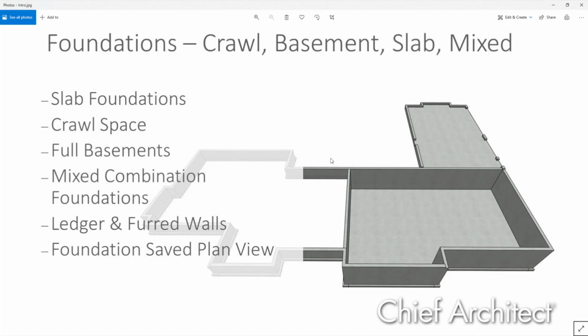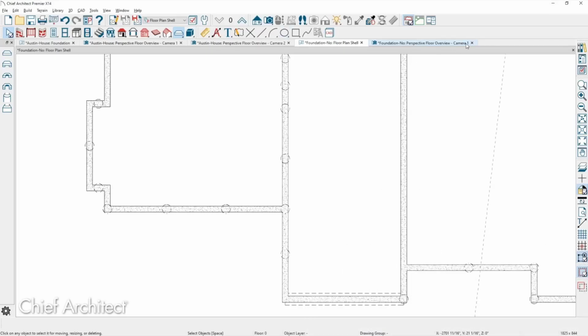You're using a stem wall to build your slabs, and in some places you need a load-bearing wall to have an additional slab footing underneath of it. Is that right? Correct. It's like the monolithic slab beams. It's the way it's drawn. It's got a 45 on the bottom. It's only a thickened 8-inch slab.